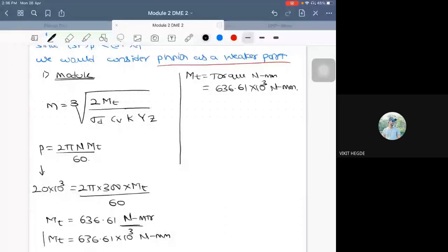That's great. Next, do I have the design stress? Yes, sir. 120 MPa. So again, which one do I have to take? Should I take it for the gear or for the pinion? Pinion, isn't it? So I would take it for the pinion. How much is the value? 120 MPa. Okay, that's great. In the same unit, it has to be substituted there.